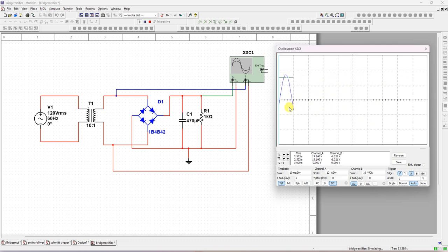Okay, it is converting AC into DC, and you can observe the output is a little bit less than the peak because two diodes are conducting at a time. Each diode will consume some 0.6 V, so that much voltage is reduced. So what is the DC voltage you are going to get here? That you can check out. Channel B is output, green color.